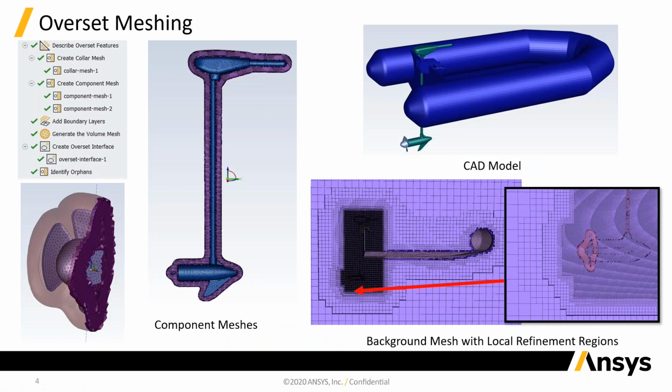Another technology that's been gradually introduced over the last few years is overset meshing. And you can now set up overset meshing in that fault-tolerant workflow. So what does overset meshing mean? What it means is if we want to model this runabout boat here with a propeller and that on, and we want great flexibility of how we change the direction and that, we can now do that by putting a high quality mesh around that object, the whole impeller and drive train here.